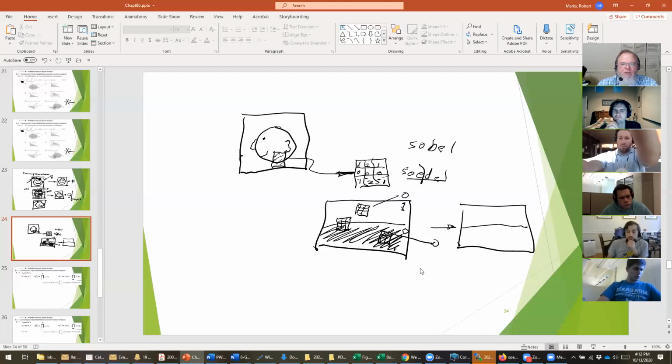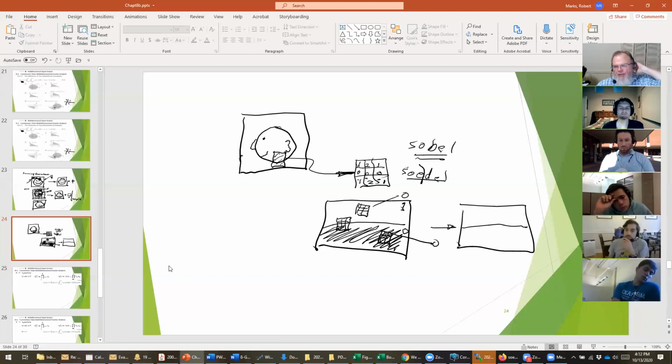So there are different Sobel operators for different detection. If you're doing image processing, you have a Sobel operator that catches the horizontal, the vertical, and another Sobel operator that catches all of the edges. And so that is another example of the two-dimensional convolution. I mentioned that hopefully to get you to see some everyday applications of convolution as we do the two-dimensional convolution.